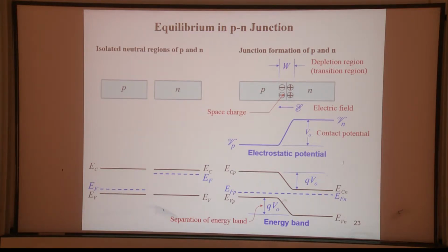However, if you want to build a canal between these two seas, then you need to find a way to balance the two sea levels. Otherwise, water will always flow from one side to the other, right? This is exactly what happens in the PN junction. When we force them to contact each other, the sea level has to be the same. Since you connect them together, they are not separated anymore, so they will adjust each other until the Fermi levels are at the same height. All right?